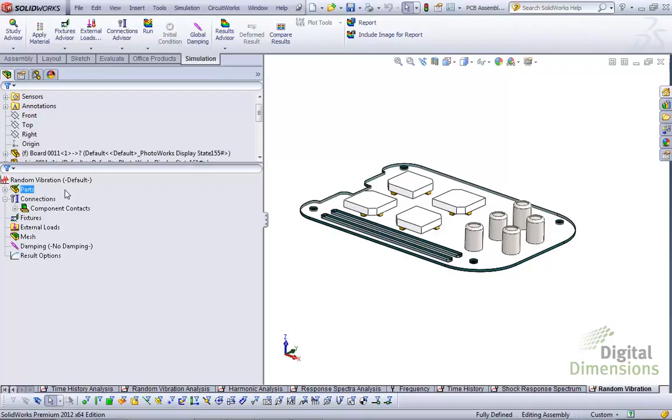By the way, if you want to compare random vibrations to a real-world example, take a look at the stresses on, let's say, an aircraft during takeoff. Typically your parts are going to be exposed to a shock loading because you get an initial impulse of load. If you want to find out how your parts are going to react once the airplane's up in the air, then you want to take a look at a random vibration simulation, because it's not an impulsive load. It's just going to be a random vibration loading, which is going to be non-periodic.